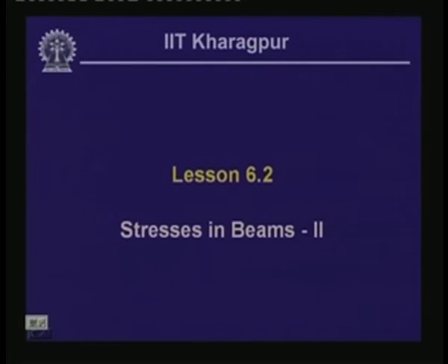Welcome to the second lesson of the 6th module, which is on stresses in beams part 2. In fact, in the last lesson of this particular module, we have discussed the effect of bending and consequently the stresses in a beam due to bending, and we have seen how to evaluate stress at any point due to the loads which are acting on the beam, and consequently if it is acted on by pure bending, then what will be the stresses. Now, which we have defined as the bending equation or the flexure equation.